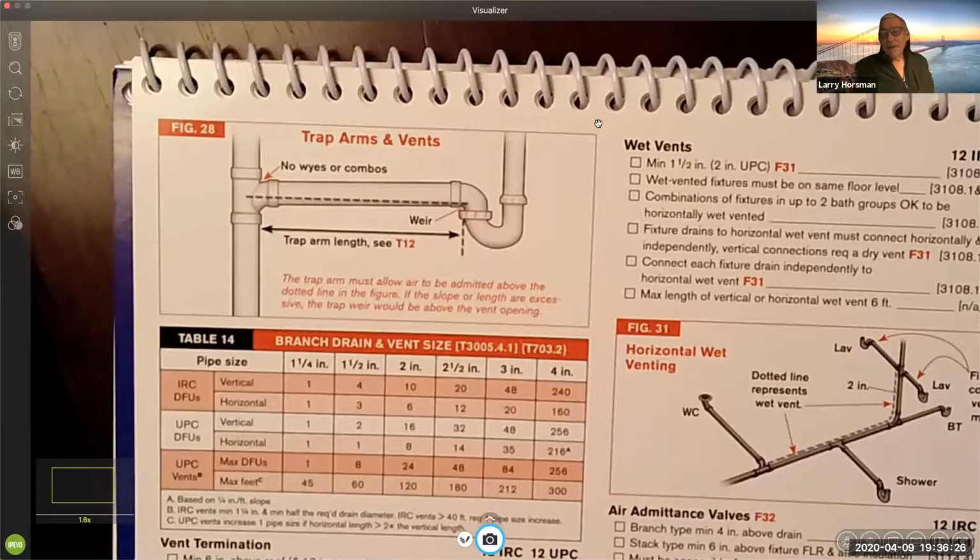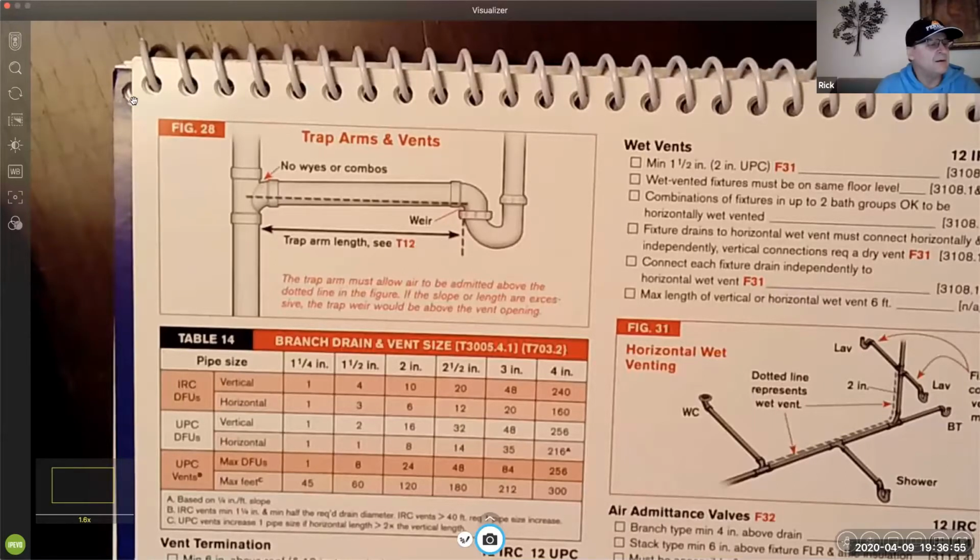And I wanted the water to go away, but unless I periodically pour water in there, you're going to have problems with the trap seal evaporating. So I put in a trap seal primer. And then if you put in a trap seal primer, you need to have an accessible box or something so you can get in and service it or replace it if you need to. Wow. That's thinking ahead, Larry. That's a good one.